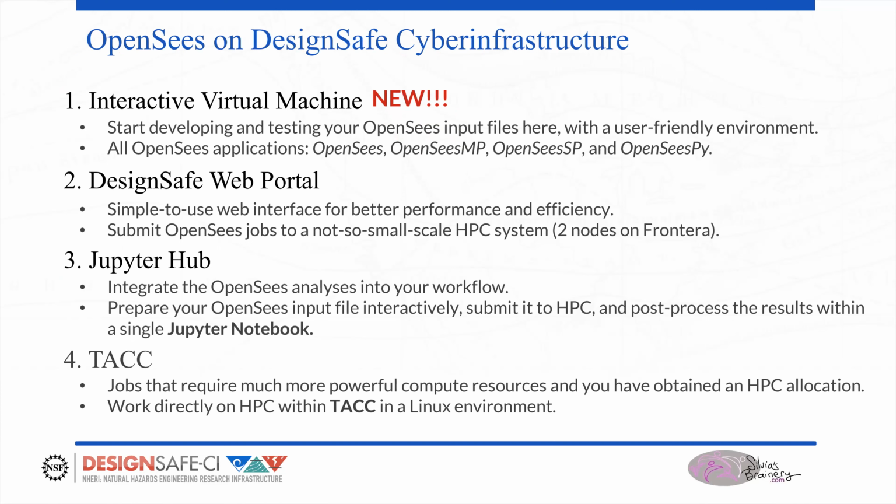So 1 is this new thing, the interactive virtual machine that I'll tell you about. It's really cool. It's got a user-friendly environment because it's a Jupyter Hub type of environment, but it's preset and it's already preloaded with OpenSees, OpenSeesMP, SP, as well as OpenSeesPy. And you can run them interactively. Of course, you can't really run OpenSeesMP interactively, writing in each line of input, but you can run it, call OpenSeesMP, run it, it gives you an error, fix your script, and I will show you the workflow there.